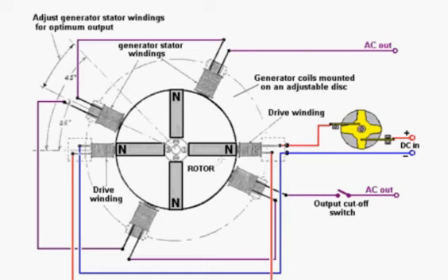Now that's fine as it goes, but then the rotor continues on round. And the cunning part on this is the power to the drive coil is then cut off. And when it's cut off, you get a back EMF pulse in the coil, and that reverses the magnetism of the coil, and that pushes the rotor on its way instead of hindering it. The same is done for the pickup coils.